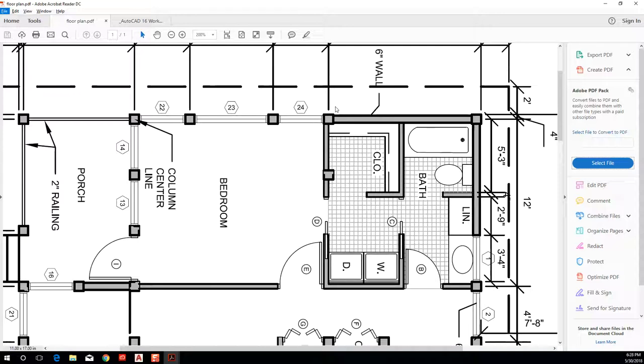So I'm reading the walls, I'm reading the windows, right? I'm reading the appliances and the millwork. And then I'm kind of reading this dashed line in the closet, which in this case looks like it's indicating the hanging bar, the rod in the closet, okay? And then my eye goes to the flooring, which is a gray tone and a less important pen weight. So that's graphically how I'm going to read a set of drawings.